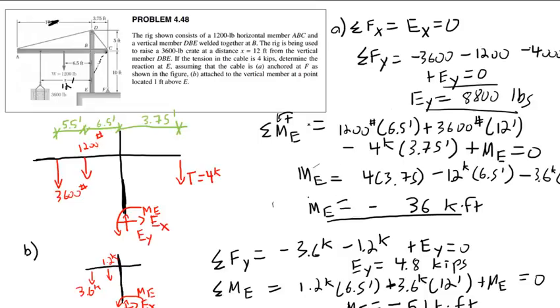So notice what we've done. Notice what this rope allows. Notice what anchoring this into the ground allows. We essentially have two different systems that we could support this crane with. One, we're supporting it with the anchoring point on the ground. The other, we're supporting it without. Here we have a higher vertical reaction. Notice the vertical reaction at point E, in this case here, is a full 4,000 pounds higher than the vertical reaction in this point here.